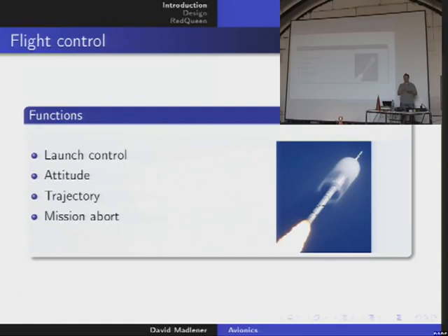So if something goes totally wrong, let's say up there were astronauts, and the solid rocket motor, they are sitting on hundreds of tons of explosive, something goes wrong. And avionics notices this by looking at, for example, pressure sensors in the motor, and they see a spike in the pressure that goes beyond some defined point, and know this rocket motor will now explode. And then this avionics is faster than any human could react, and then it will activate the ejection system to bring the astronauts to safety.